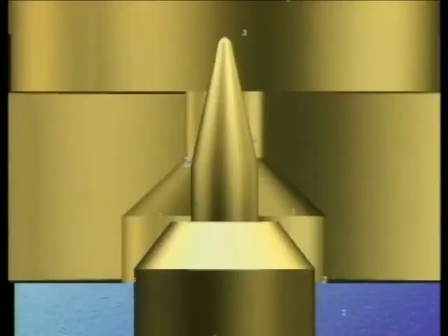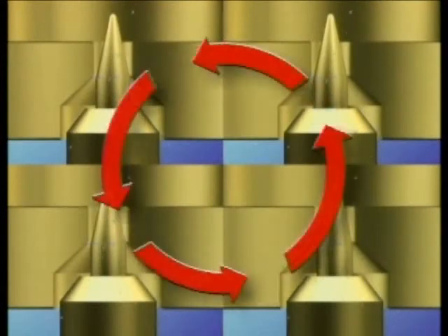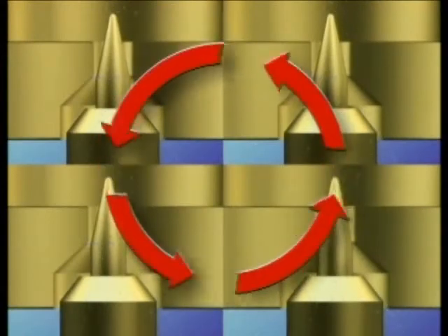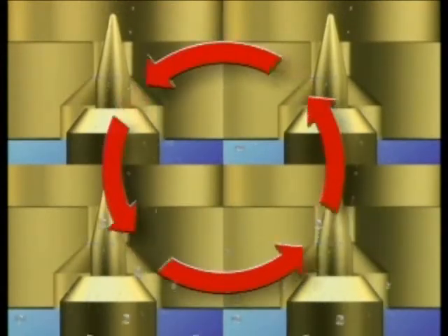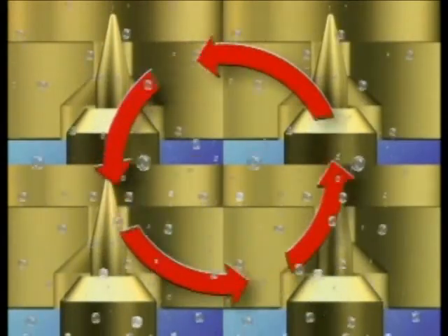When an engine runs under lean conditions, the temperature of the engine rises, and so does the temperature of the fuel. This, in turn, causes another increase in bubble production, and more bubbles lodge between the needle and the main jet. This creates even leaner conditions, which raises temperatures, which creates more bubbles, and on in a vicious circle. Now our carburetor has become little more than a bubble-building machine.